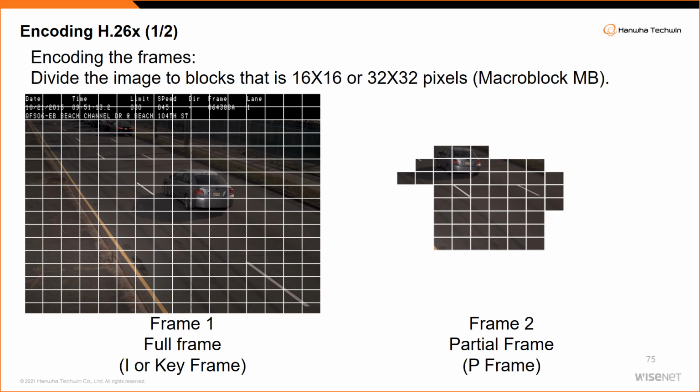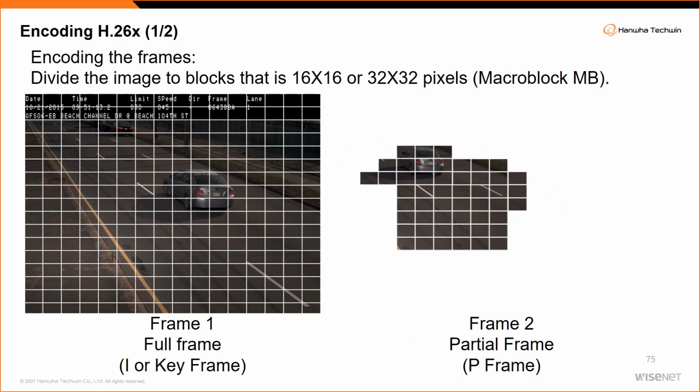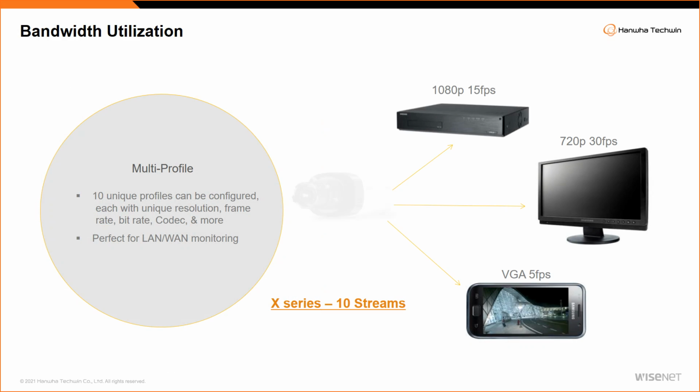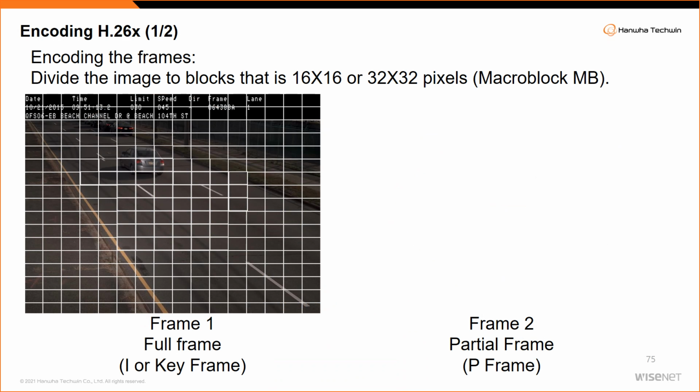Now, after this merge, did you lose any data? Not really. It's called compression. Make sure you don't lose the usable data, right? That's the objective of this codec. So H.265 is not going to reduce the quality. H.265, although a higher compression standard, is a new method. It actually can improve the image quality in some aspects.